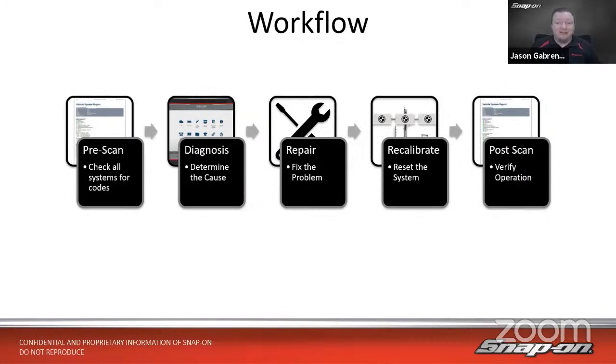But then, of course, in this case, we don't get any codes. Then what do we need to do? Well, we need to go through a diagnosis. Code or not, you still need to diagnose the cause of the problem, right? So that's where we will spend a lot of our time, trying to diagnose. And then after we've decided on what the problem is, we will repair the problem, right? Fix it. Do I need to replace something? Maybe it's a bad mass airflow sensor. Maybe I have a vacuum leak somewhere, or a fuel pressure issue. Whatever we need to do, we fix the problem.